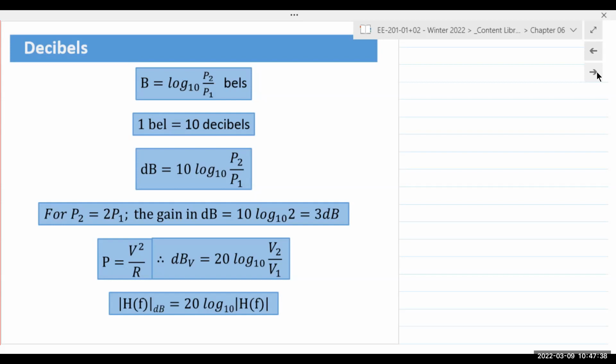But the point in terms of power is, if you want to increase or decrease the volume, a normal typical human ear can discern a 3 dB change. So if it's 1 dB or 2 dB, most people may not be able to hear it. Most people would require a 3 dB change, but a 3 dB change requires a doubling of the power. And that's the important point. You would need to double the power output to change it at least 3 dB.